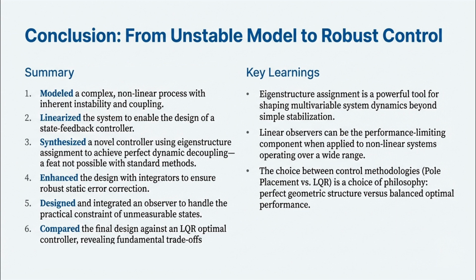My key learnings were eigenstructures and also the decoupling of eigenstructures, as it's a powerful tool, and just using place as many tutorials do is not the best idea if needed. I validated my knowledge that linearized observers only work near the linearization point, and I compared pole placement with LQR.